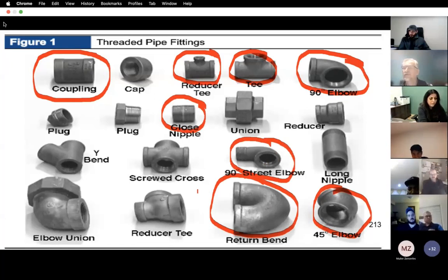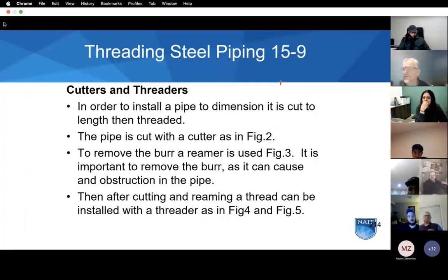And as we get to, I'm looking for a union. When we get all the pieces hooked together, we need to hook it to some existing piping. Generally, we put in a union, and this is a joint that allows us to take out a piece or a part of the piping network for disassembly.